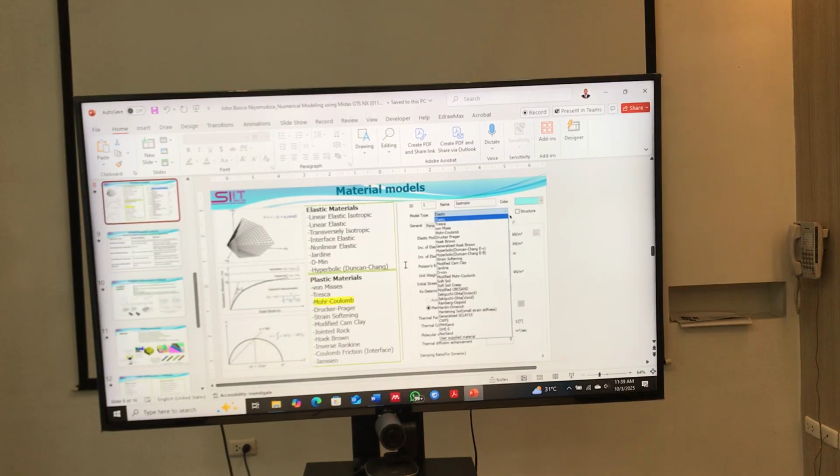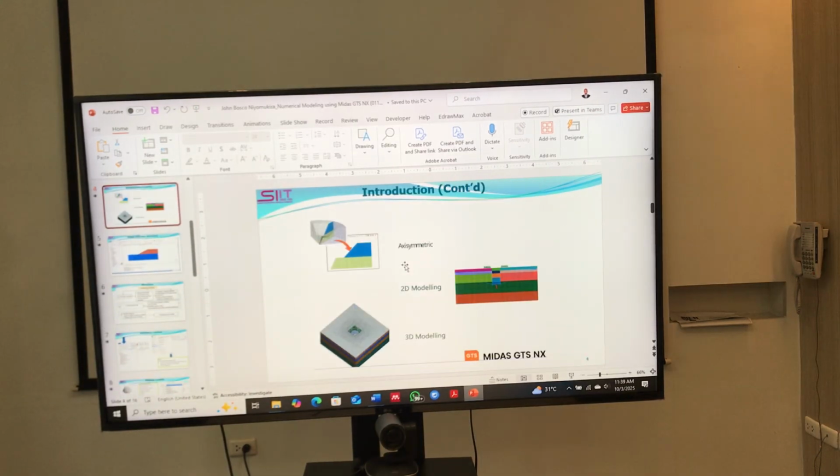Anyway, in actually understanding things, you also need to understand the theory behind. You need to first read the theory. After understanding it, the reason I'm not used to the water level is that I have not been considering it. For my slope, I assumed everything to be unsaturated. But in my case, the saturated water level is the most important. In consolidation, water pressure and how it behaves is so important.